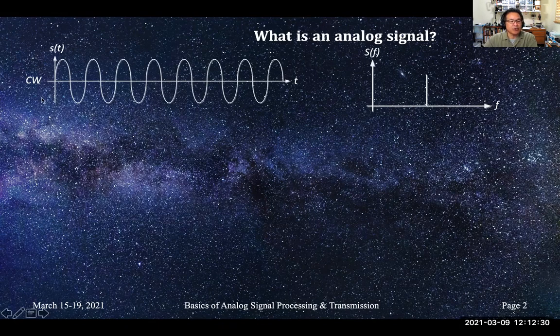This is a pure sinusoidal signal with respect to time, voltage versus time. I've denoted it as a continuous wave signal. Its frequency domain response, power versus frequency, is shown here, where all the energy in this analog signal is confined to one frequency.